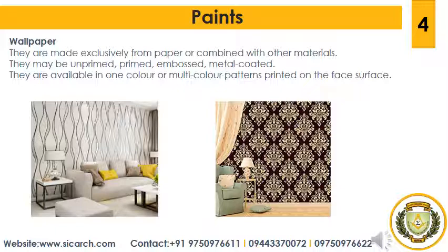The surface on which the wallpaper is to be fixed is dried, leveled and made free from chalk or lime solution. All the cracks and slits are filled with lime gypsum solution. The surface is then pasted with wrapping paper or newspapers by applying suitable paste. The wallpaper which is available in rolls is then hung very carefully on the surface and the continuity of the pattern or design on wallpaper is maintained. The wallpaper is available in a great variety of patterns and colors.